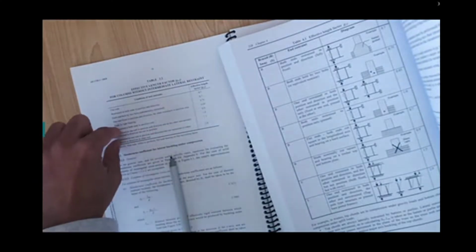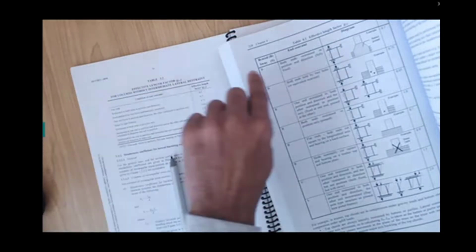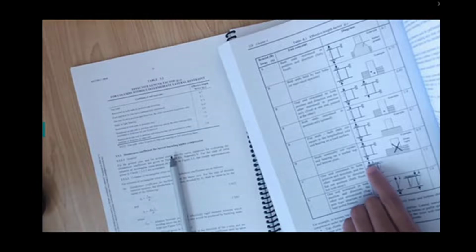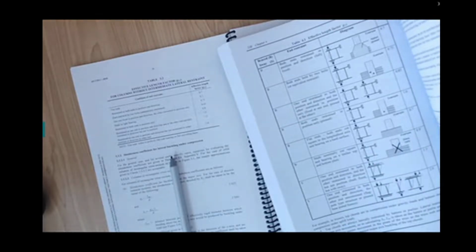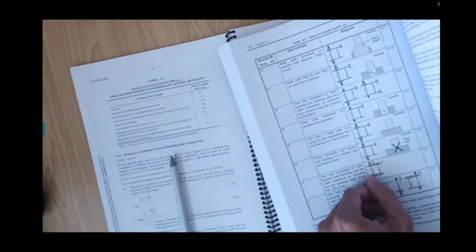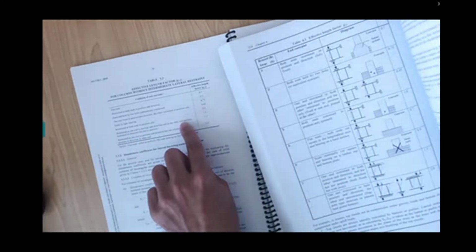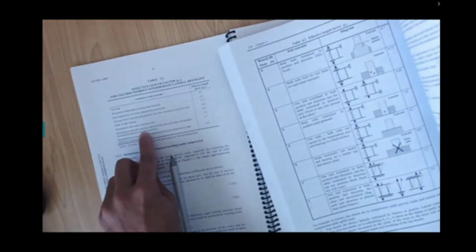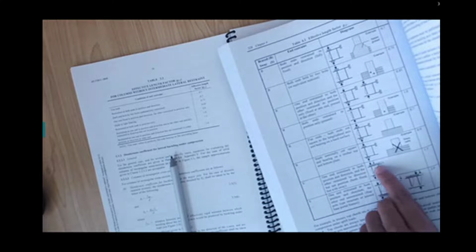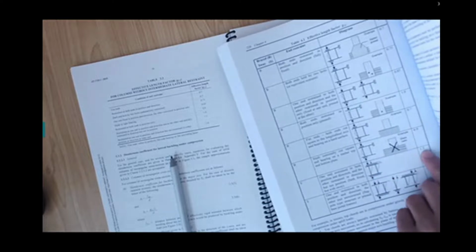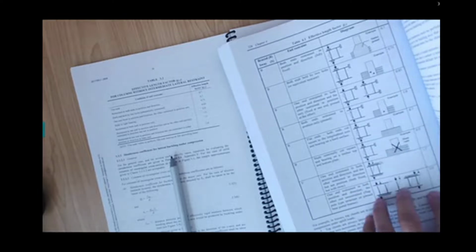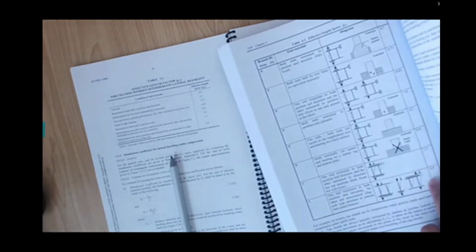So now this is coming to the sway frame, or unbraced. Your one end is fixed, but the other end is moving away, as you can see. So restrained at one end in direction, that is the bottom one, and the other end partially restrained in direction, but not in position. So rotation is restrained, but displacement is happening. So it's 1.5, very bad. They don't like this one. This is even the worst one. You never want to do this one.